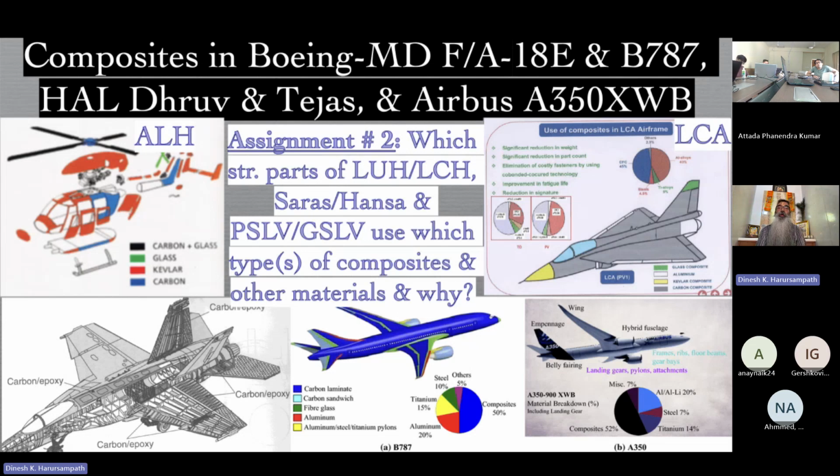The most common and sought after composite for a lot of aerospace applications, purely by dint of its performance in spite of its cost, is the carbon fiber epoxy composite. Slowly, from the point of view of sustainability, epoxies are being replaced by thermoplastic matrices like PEEK, polyether ether ketone, etc. But overall, you would see it's mostly carbon and polymer matrix composites that are typically used.